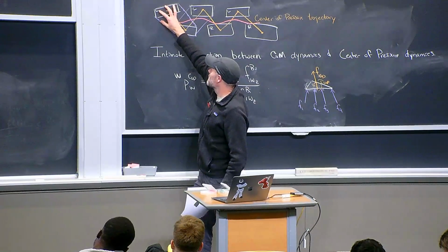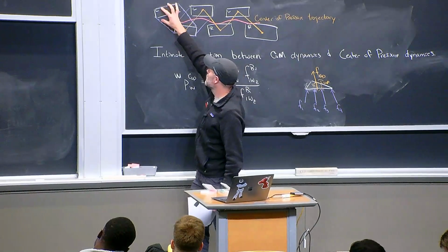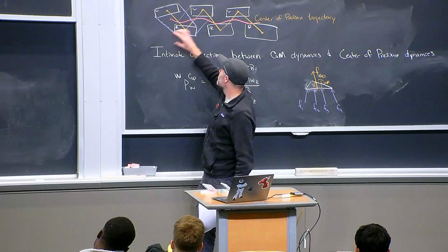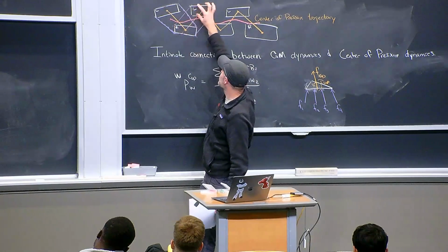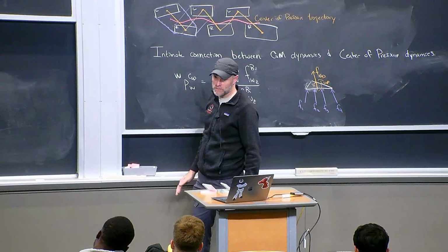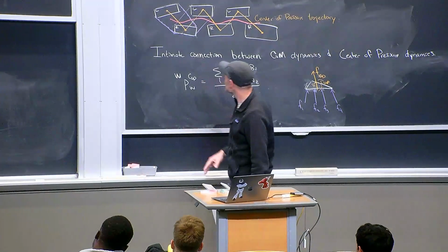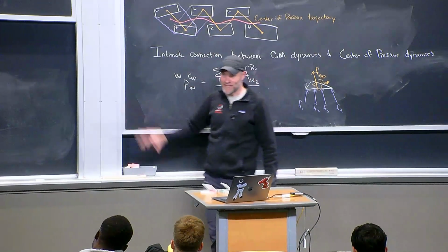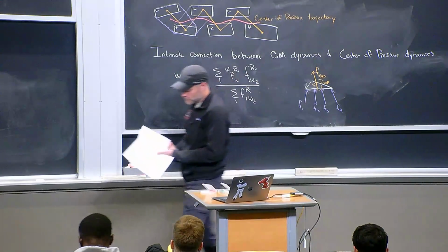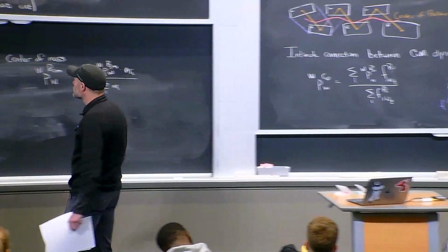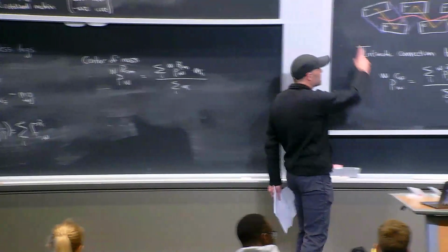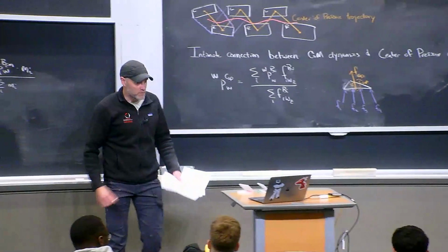Okay, now to your specific question. I'm going to think about a sequence of support polygons. First, I'll start with, let's say, 2 feet on the ground. And then instantaneously, I pick up this foot, and my support polygon becomes just this foot. Until I set it down, I'm on just this foot. And as soon as I set it down, I have the ability to generate forces from that whole convex hull. So back to my original picture of the satellite, these are the pictures of the things that get generated, which constrain where your forces can come from. And once you have the center of mass trajectory, it turns out you can just solve for the kinematics and play out and get these kinds of things.